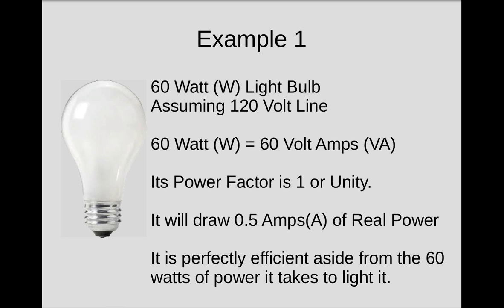240 volt service is essentially just two 120 legs with a common neutral. Over in Europe, they use 240 volts to the appliance as opposed to 120, and a lot of European services are 50 hertz as opposed to 60 hertz. That's why if you go overseas, you'll notice the TVs are a lot dimmer. The refresh rate on the devices over there is different than it is in the United States. That's a different topic for a different video.